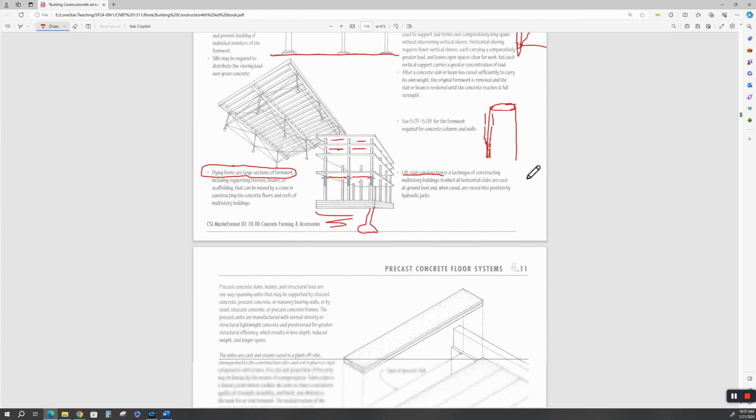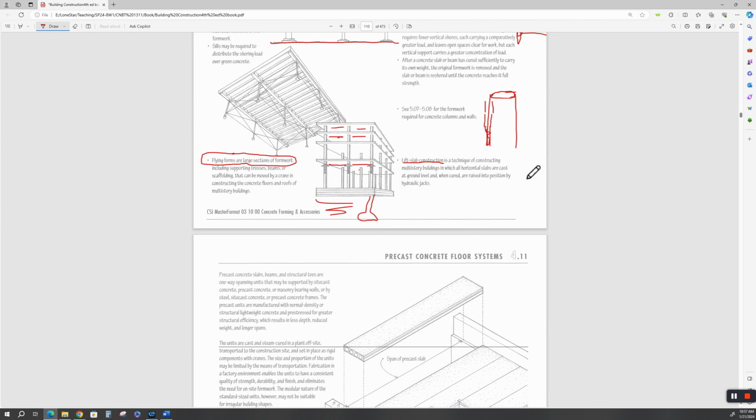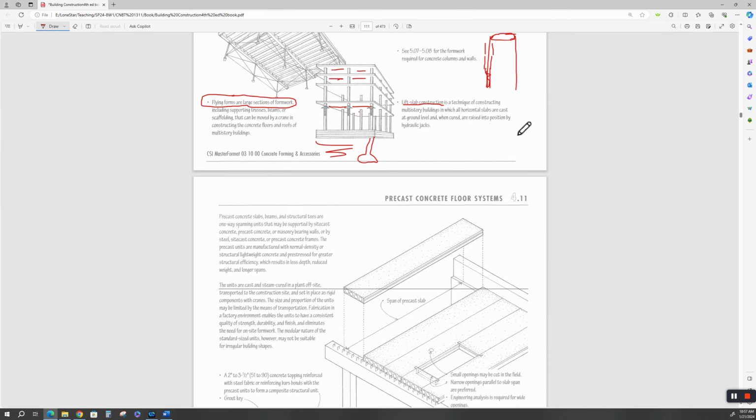I've got a huge lift station out at Southwest Wastewater Treatment Plant. That's how we did that. It was a round lift station. Had a big cutting edge underneath it. So it saves you from having to excavate, put retaining walls in, and then build it and then backfill it.